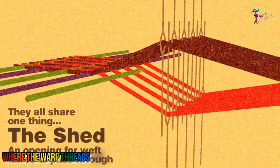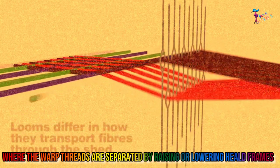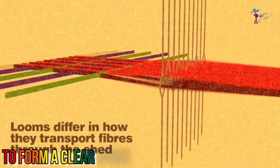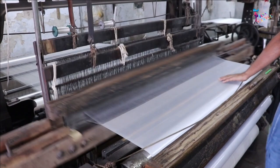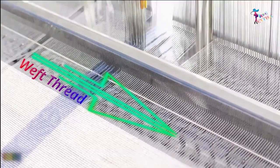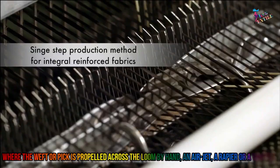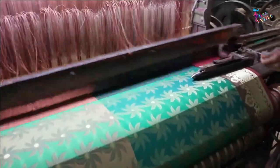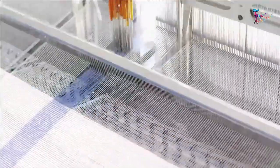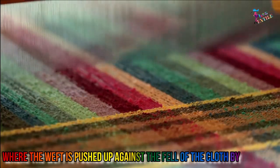Shedding, where the warp threads are separated by raising or lowering heddle frames to form a clear space where the pick can pass. Picking, where the weft or pick is propelled across the loom by hand, an air jet, a rapier, or a shuttle. Beating up or battening, where the weft is pushed up against the fell of the cloth by the reed.